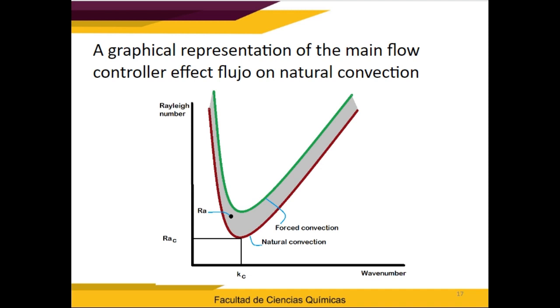One side effect of this strategy is that the controller will always drive the fluid layer conditions to meet those of criticality. As this is the first approximation to the problem, I should recognize that perhaps better results can be achieved if a full proportional integral derivative control signal is used, not considered here. This approximation is also based on continuous modifications to the basic state of the velocity, which could also seem odd, but I think that this is physically feasible.